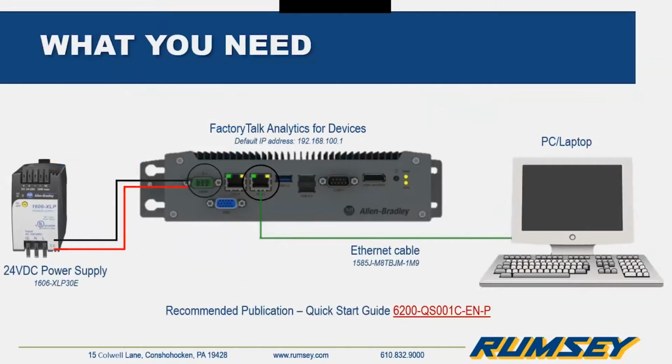This is what is recommended to connect to the appliance for the first time. Simple power supply, the FactoryTalk Analytics for devices hardware, an Ethernet cable to a laptop or PLC, and then obviously any other devices that you want to scan and collect the data from. So it's really nothing fancy. In fact, you might be familiar with the setup already. The appliance has a default IP address that you connect to make the initial configuration easy. And then obviously they do have a recommended start guide for any additional information going through that process.